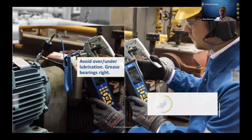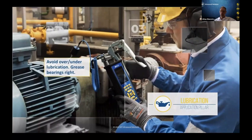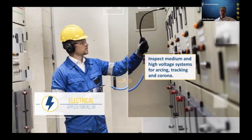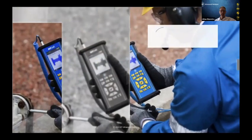The next application pillar is lubrication. We want to avoid over and under lubrication of rolling element bearings. And when I don't have a good lubrication film in my bearings, what do I have? I have friction, and friction starts with F, and it's one of our three. It's one of our FIT symptoms. So lubrication is another great application for ultrasonic technology. The one we're going to spend the most time on is electrical, so let me jump past that one and get to the other ones.